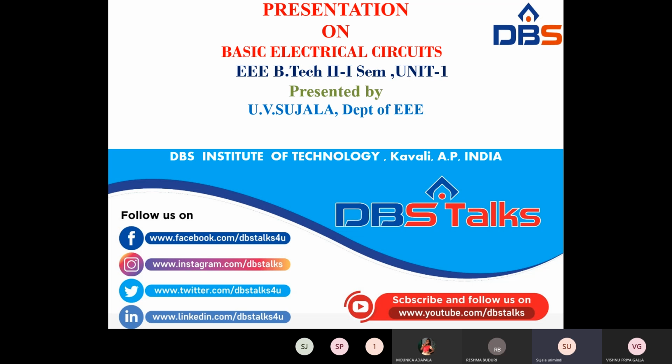So when it comes to the leaving of the node, I3 and I4 are leaving the node. For I1, I am telling that the algebraic sum of the currents is equal to 0. So current entering is equal to current leaving. When you observe that I1 is entering the node and I2 is entering the node, that is I1 plus I2. And I3 and I4 are leaving the node, that is I3 plus I4.